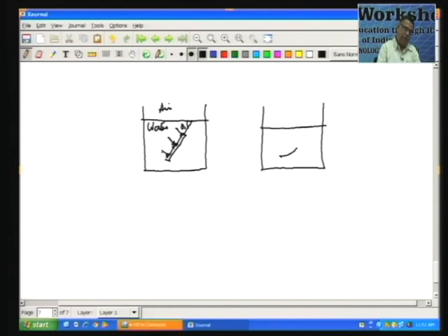So, let us say you have a solid surface which is now curved. Now, if I take an area element here, the force due to the pressure is going to be in the direction normal to this. Now, if I take another area element, its orientation has changed. The force is going to be again normal to this. I can see that the direction of this force and this force, elemental forces, are going to be different. So, when you want to find the force on a curved surface, you have to account for both the change in the magnitude of the force as well as the direction.